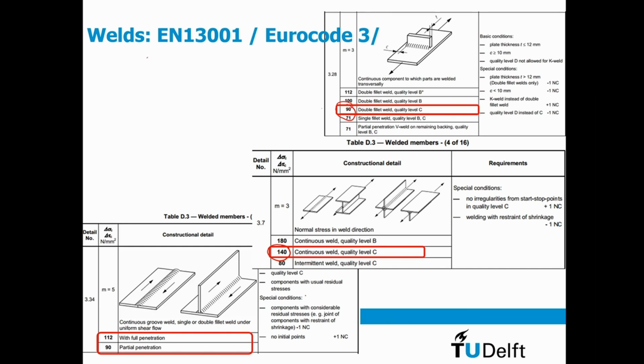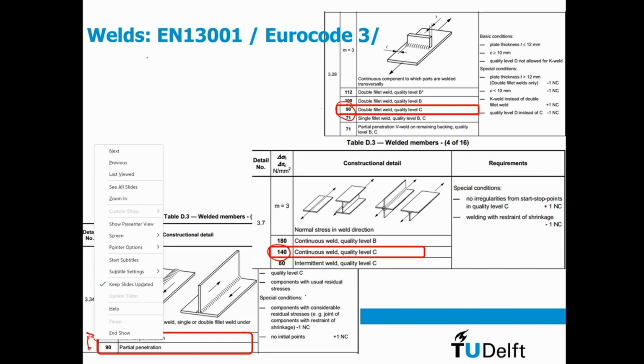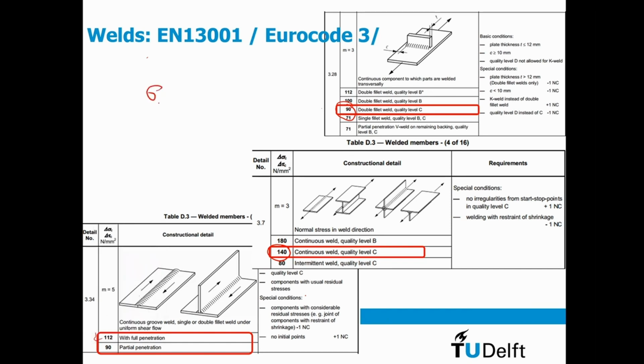And what we also see is that shear does not cause a lot of fatigue, and the reason of that is, although this is a lower limit, of course, but if we take the equivalent stress, then the difference between tau and a simple tension stress is times the square root of 3.